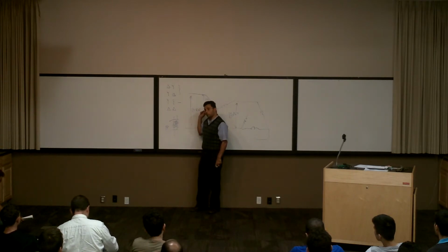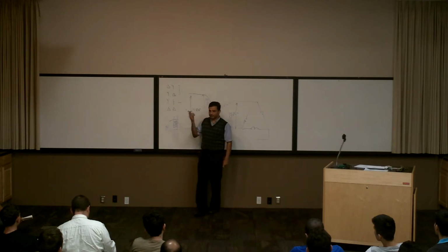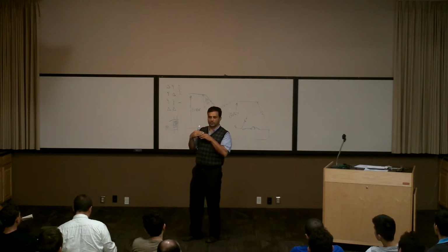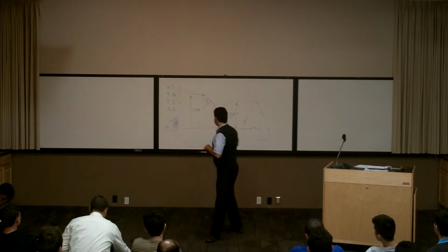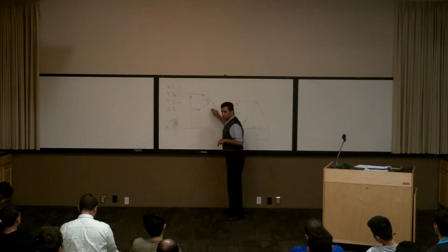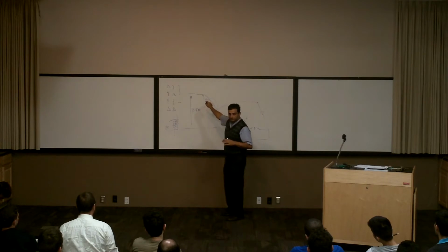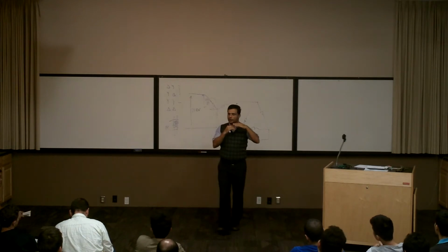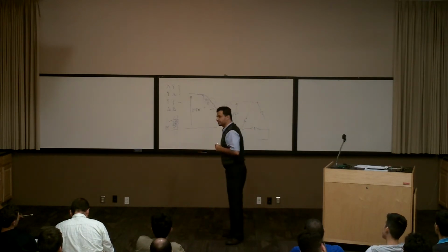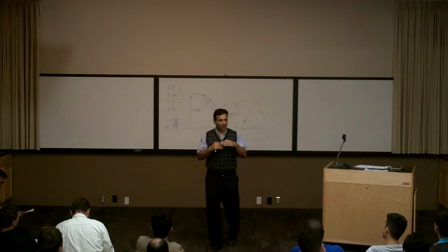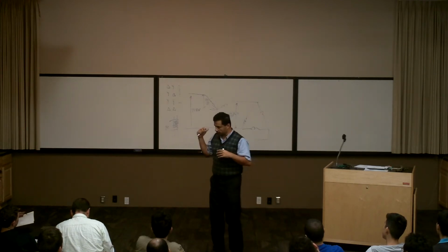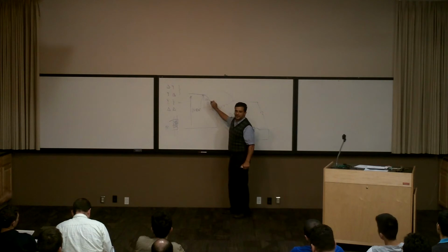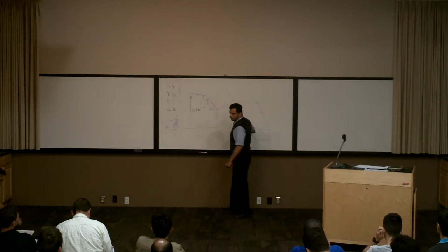But when you get to, for example, 400 kV, and you have 10 turns, obviously there is a big voltage between the two layers, right? They call it isolation voltage. So in this case, it would be much easier to build it because the voltage is going to be maybe 60% of this voltage, right? For example, here between the two turns is, for example, 10 kV or 6 kV. So it's much easier to provide the isolation compared to the delta connection. So in general, I'm saying, Y connection needs less isolation voltage compared to the delta connection.